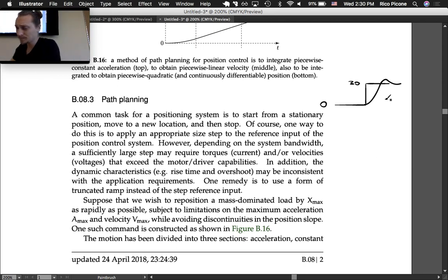For instance, your simulation would assume it was going up to 10 volts, which it can't do in reality. So your performance design is not going to be reflected unless you've gone through the process of saturating in simulation as well. It can also give rise to other issues too, like if you are flowing full current, say, through your motor.